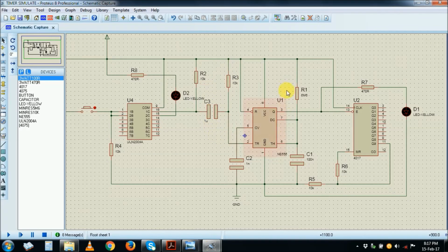So our main timing circuit is the monostable oscillator, or the monostable circuit, using the 555 timer. You will find that you can also use the dual 555 timer, which is the NE556. The NE556 has got these two timers in it, and two power pins, number 8 here and number 1, which is power, a positive, and ground here. But the NE556, or a different version of it, I think it's the MC3403, if I remember very well, is also the same IC, but made by Motorola. There is another dual 555 timer in a different number, but the same IC.